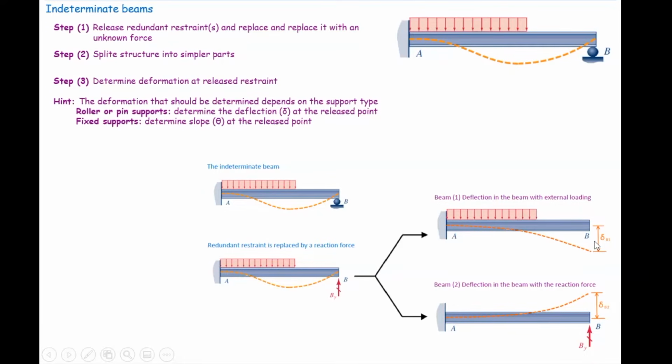All right, after we determine the deflections or deformations of the beam at different points, then we need to find out what would be the relationship between the deformations in the structure. Again, for this particular problem, we know that the beam is supported at its right end, which means that the right end should not move. In other words, the deformation that we see in these two beams should add up to 0.